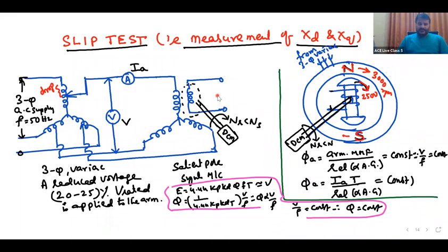The reasoning is, if the rotor is rotated at synchronous speed, what will happen? Tell me. If you rotate the rotor at synchronous speed, the armature poles are rotating at synchronous speed, so it always finds the air gap minimum only. Actually, what we have done is, this is synchronous speed, this is less than, for example 3000, 2500 RPM say.